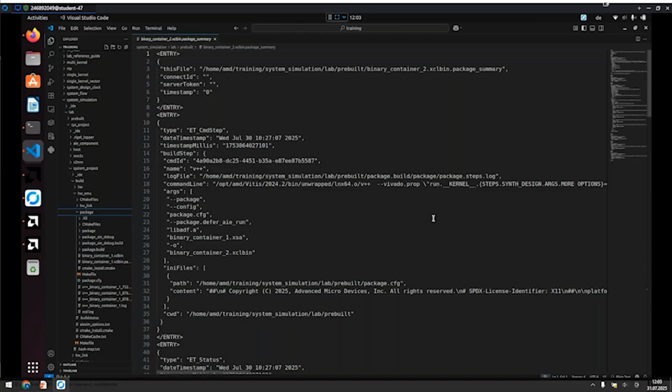Yeah, nice question. That goes to the AI Engine. In the current setup of the software, you qualify a function to be compiled against one particular AI Engine vector processor. If you want to split the function between different vector processors, you have to rewrite your C code at this point.